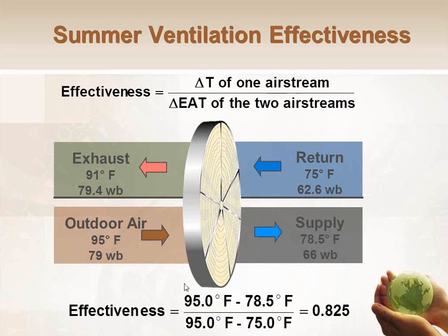Sometimes you'll hear the term efficiency, but that is not a correct term, because it's not technically using much power to get the output. If you looked at it from a pure efficiency standpoint, all the efficiency numbers would be higher than 100% because we're using waste heat recovery. So the correct term per the AHRI standards is effectiveness. What is the effectiveness of the ERV is the proper way to term that. And this shows you how that's calculated.